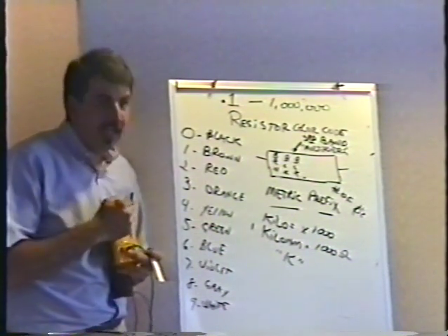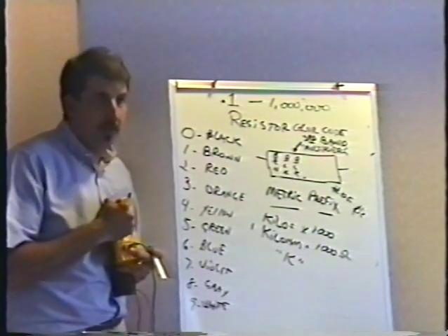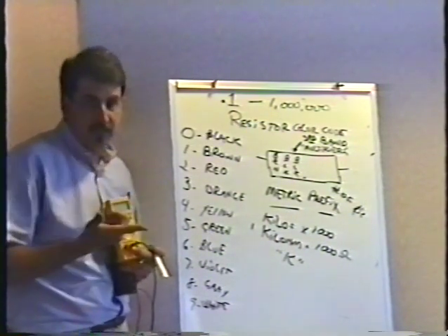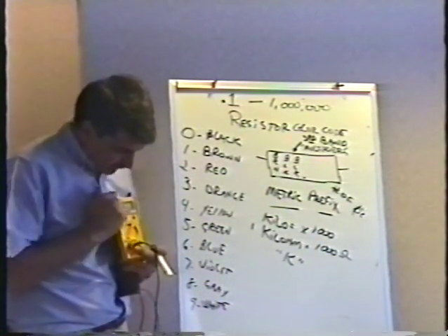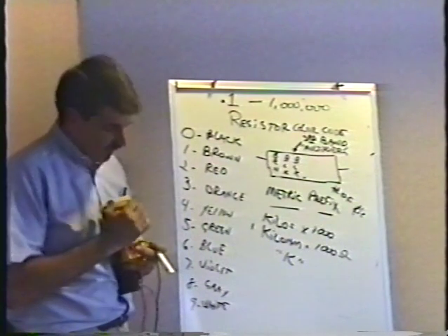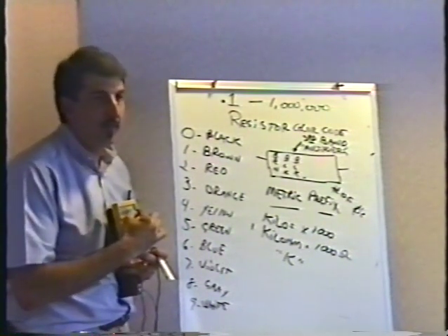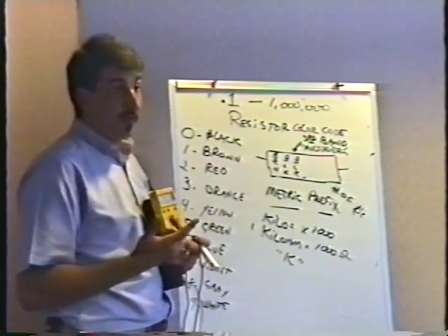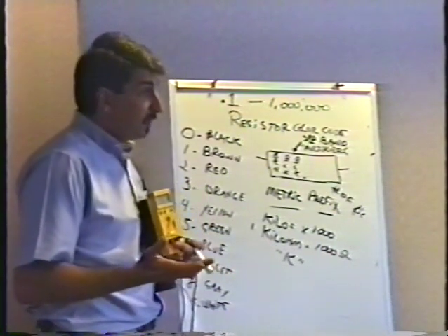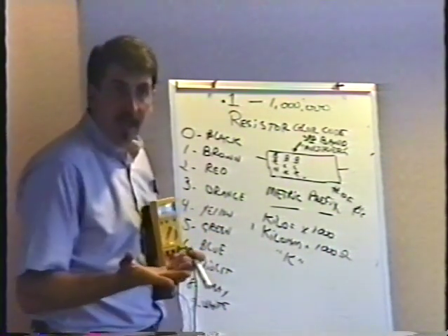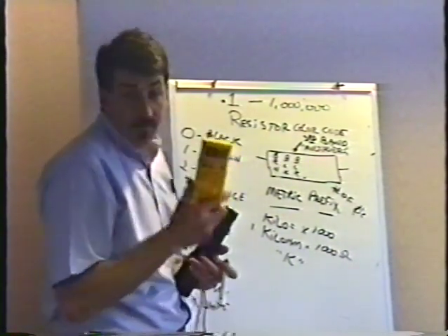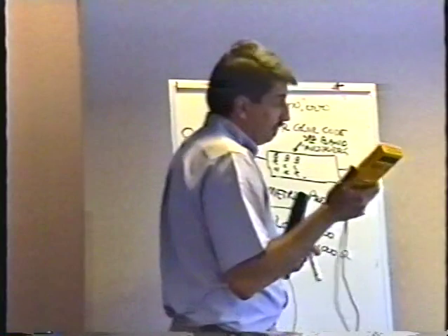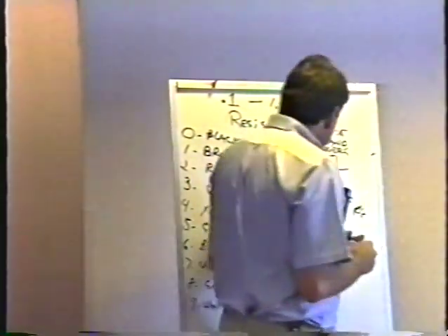You'll see a little K in the upper corner, usually, of the meter. Maybe it's real big. It depends on the meter you get. That tells you how many ohms it is. But on my meter, the K is a teeny tiny little letter in the corner. If you're not careful, you may think you're reading 10 ohms, but it's really 10K, where you won't have that problem if you have the other type of meter. But some people prefer auto-ranging meters. It really doesn't make that much difference.